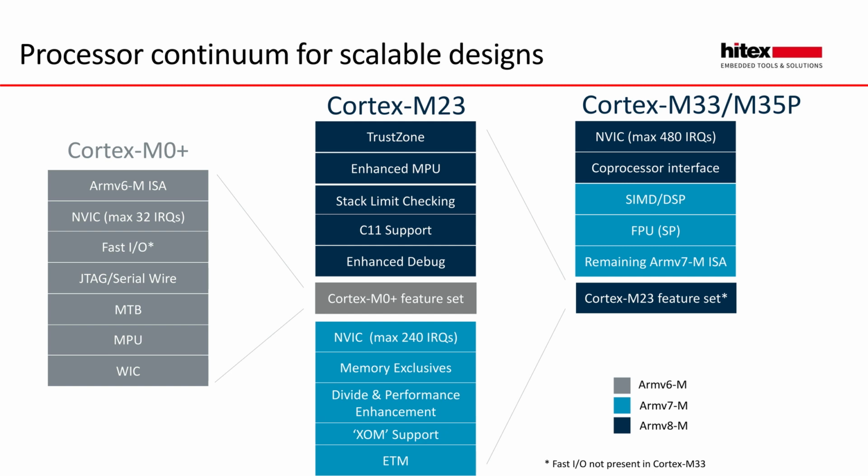Our initial reset is sitting at the start of a higher flash sector, and here we can move the non-secure vector table and relocate it to the start of our non-secure code. We also have our veneer table here. This is effectively a jump table, so that when we're running the non-secure code, we can make a call to a secure function.